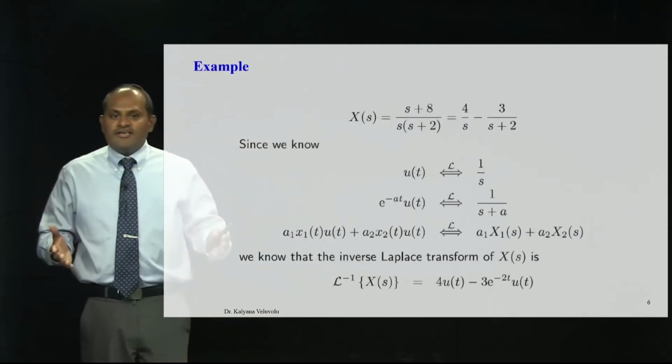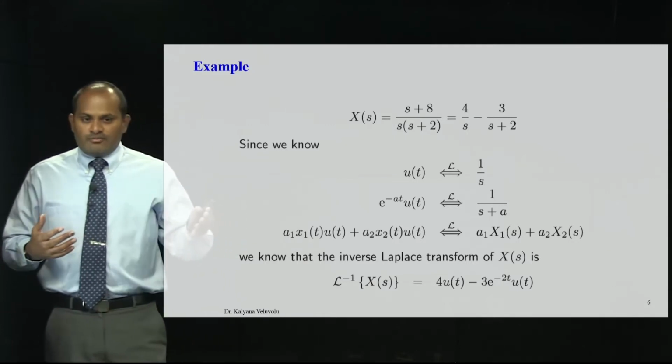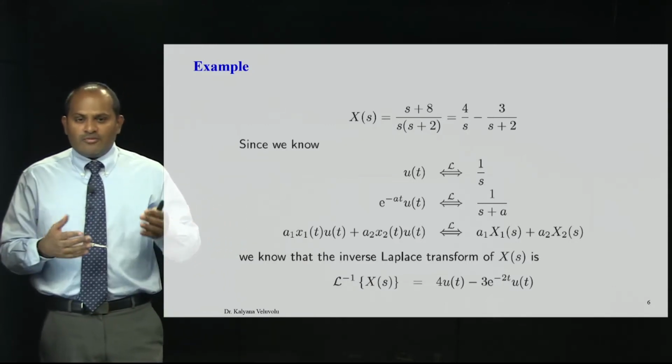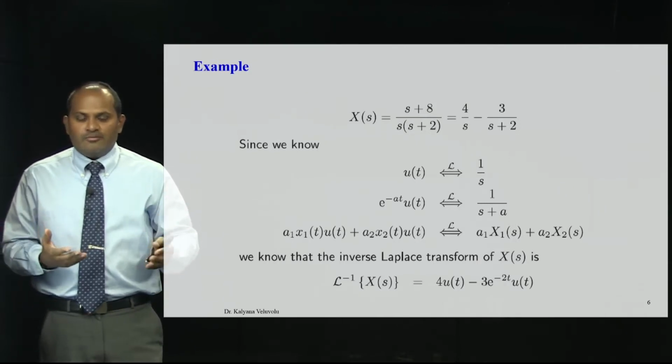So what we see here is a very good example. If you follow this example, you can apply the inverse Laplace transform to convert any frequency domain function to a time domain function.